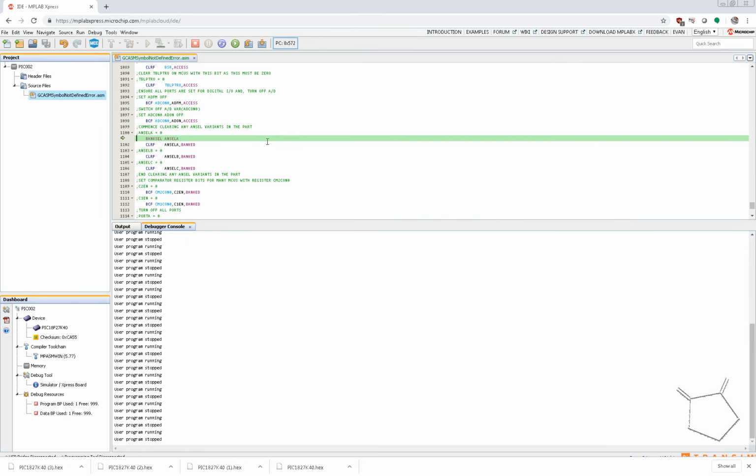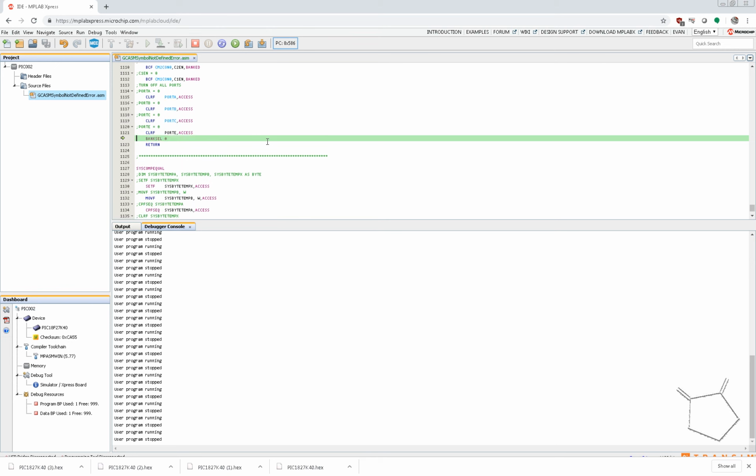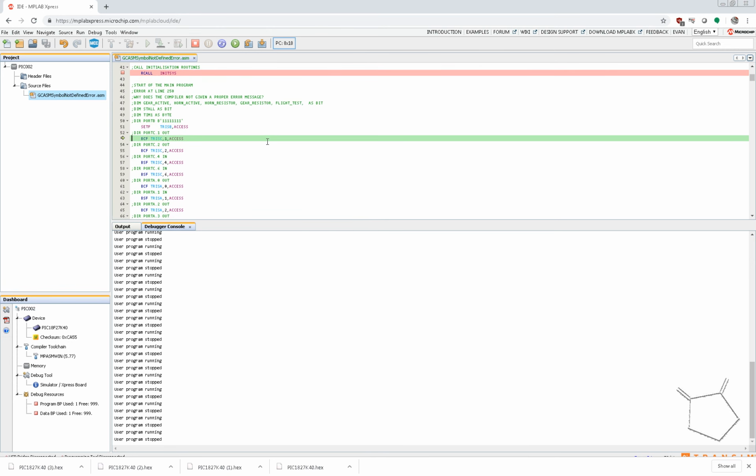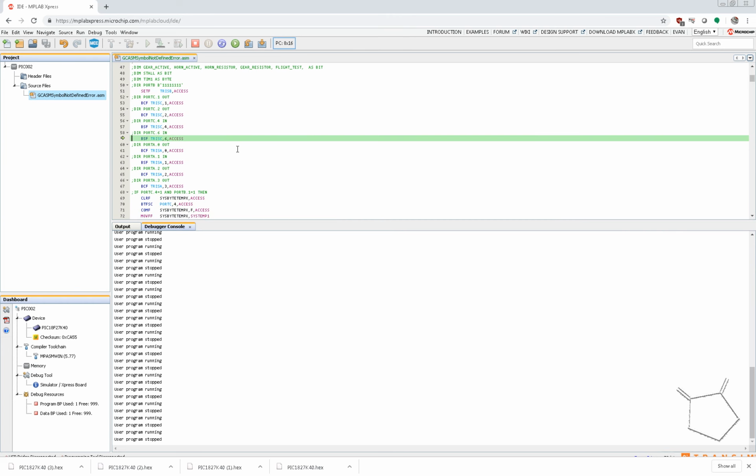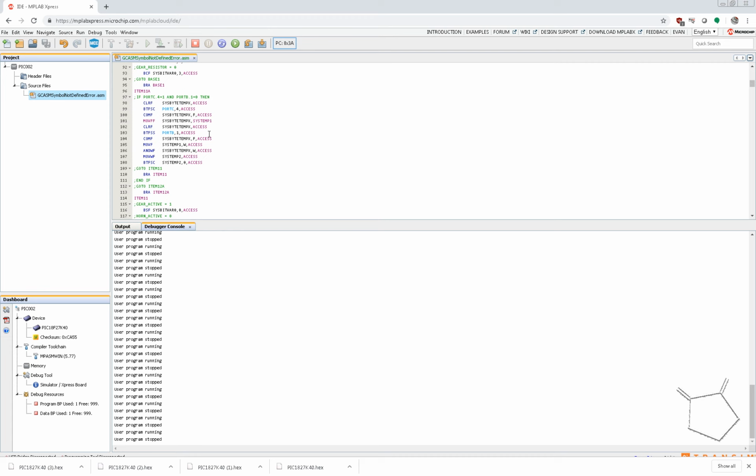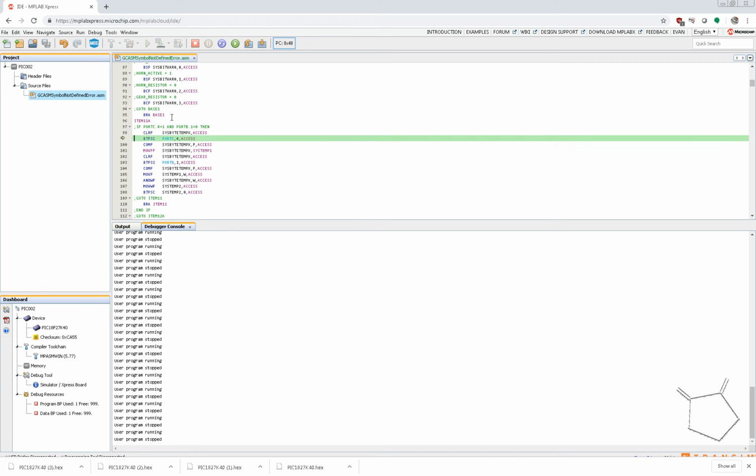And you can walk through the code yourself to see what's happening in the assembly. So it's not a mystery to you. It's now the main program. Somewhere in the main program it's got this command that's been converted into the assembler for you. And if you change program microcontroller, it will do that for you. So you can see we'll walk in the code, and as I said before, you can then see the registers changing.